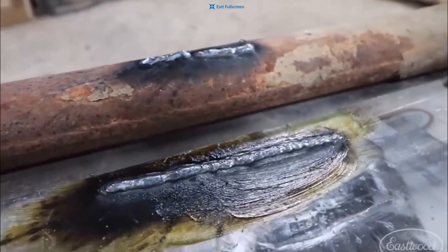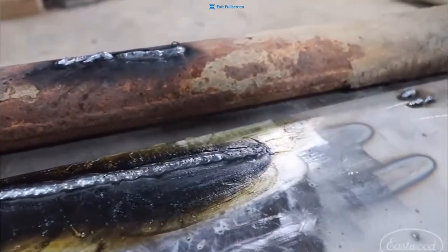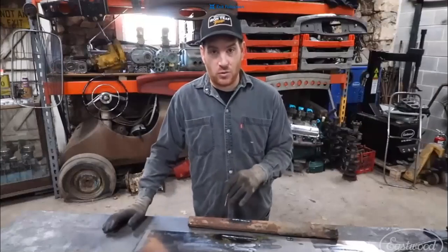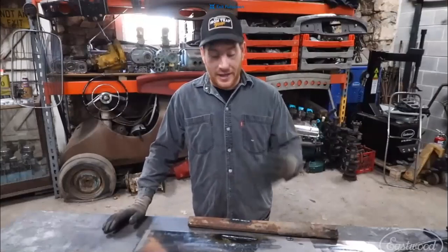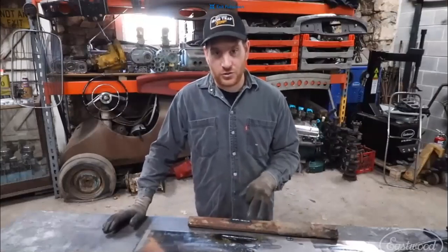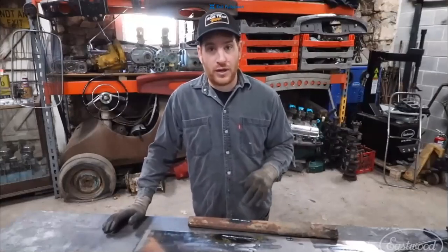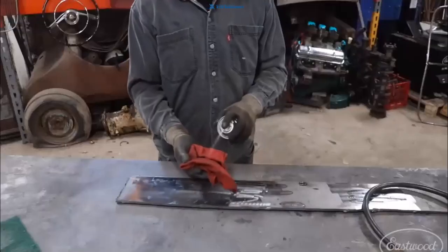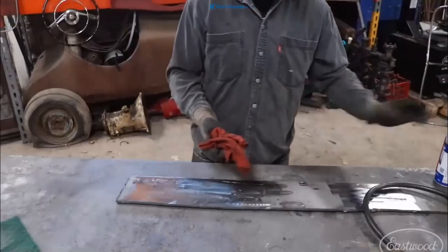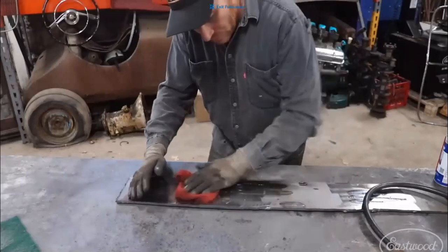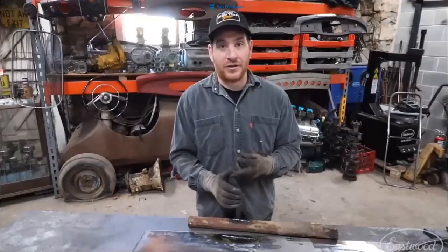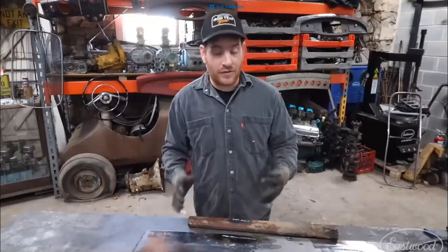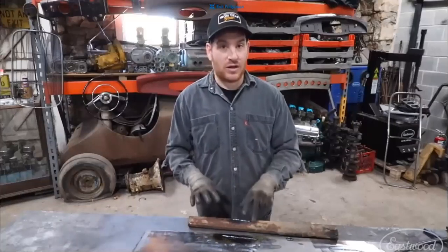So that is a good instance where if you have a part that maybe was in use, but it seems like it's clean, but it has some oil on it, or maybe you sprayed some oil on it to keep it from rusting in the shop, that could happen. So the solution for these two is basically just to clean the metal really well. Make sure that you're using low VOC prep or acetone to wipe the panel down after you clean it with an abrasive method, whether it's a media blaster, an angle grinder, a DA sander, something to take all of that off, because you don't want to weld on something that has rust present.